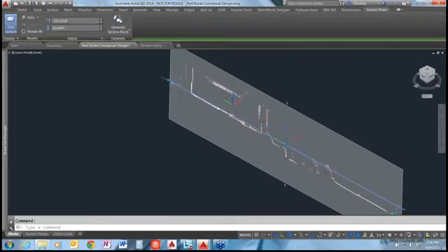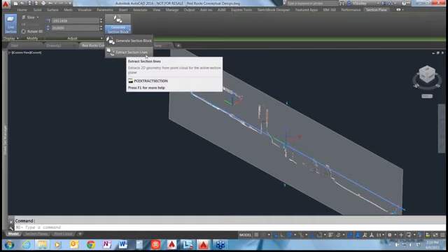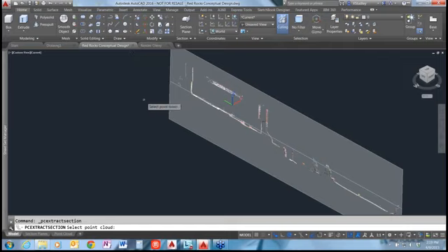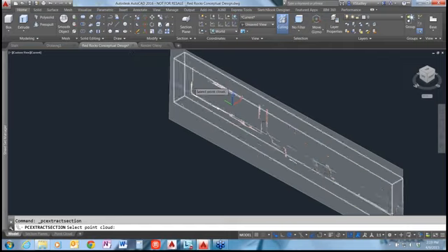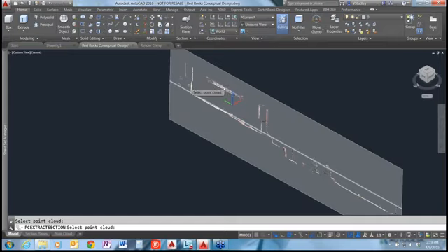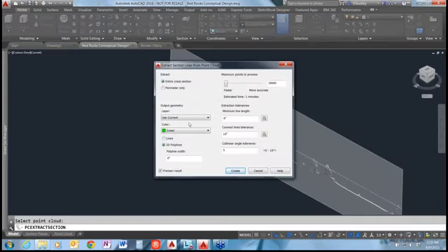And one of the cool new features that you can use with section planes and point clouds is this generate extract section lines tool. So what it's going to do is generate AutoCAD geometry on top of this point cloud based on the geometry that's been pulled in through that point cloud model. So I'm just going to select that point cloud here. Oh, come on. There we go. Okay, and it'll bring up this extract section lines from point cloud dialog box.